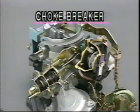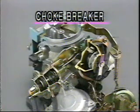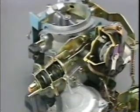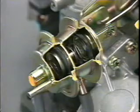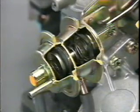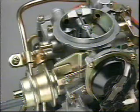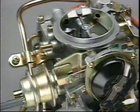Let's look at the choke breaker. During cold starts, the choke valve may remain closed, providing an overly rich mixture, which could lead to engine stalling. The choke breaker causes the choke valve to open slightly in this situation to prevent the engine from stalling.